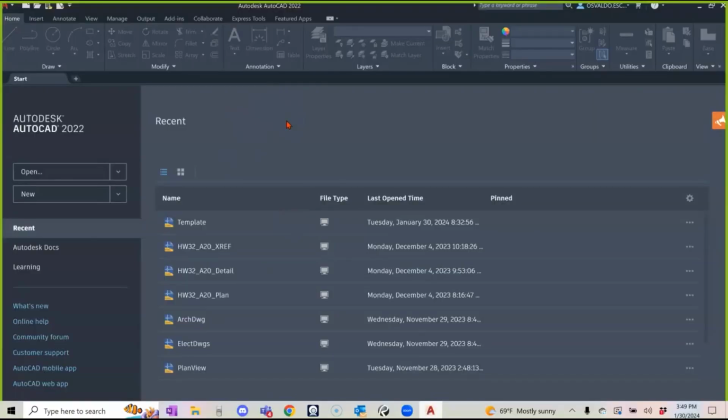You open AutoCAD, this is what you will see. Maybe a little bit slightly different than what yours might look. You click in here, I will give you a list. You click there, I will give you an icon view, like big squares, which will give you a preview. On the left bottom portion of the screen, you will have support from Autodesk, a bunch of links to the Autodesk website. In the top, you have the contextual ribbon, I think they call it.